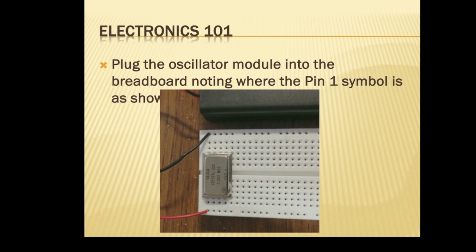Oh, that's a .01 also, that's probably why. Let's take that out. And then we're still getting, even just with the inductor, we were getting smooth pretty good, making it into the sine wave. These two values here need to be real small values, but one of those was a .01, which is way too much. And the other one was a 150, probably 15 microfarad, which is probably a little too much. So we use smaller values there. It would help smooth it, just to make it a little more round and a little less triangular. But that's the idea behind it. So looking good. It works. That's the main thing.